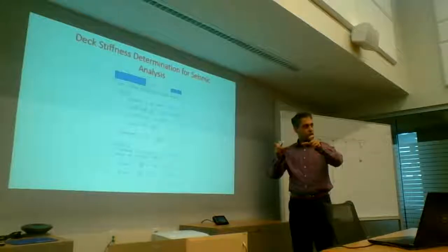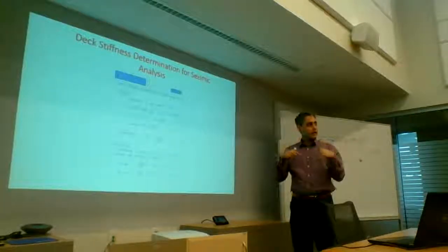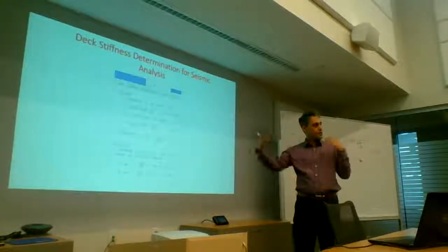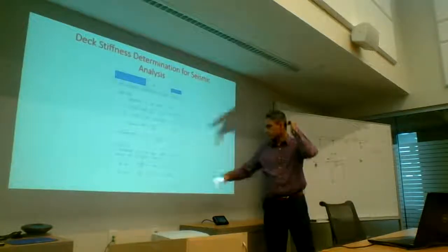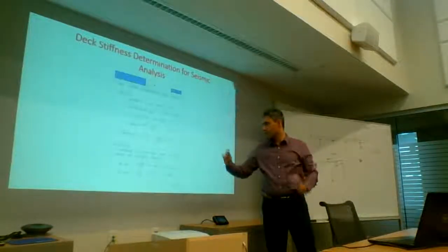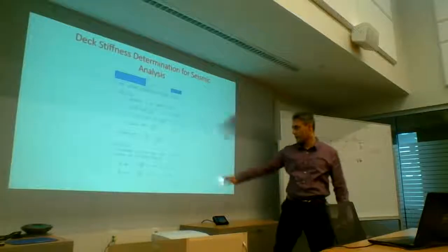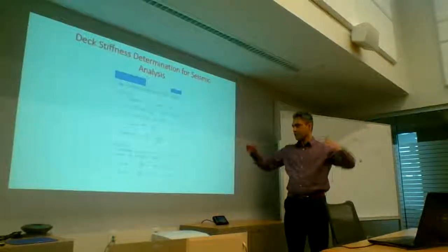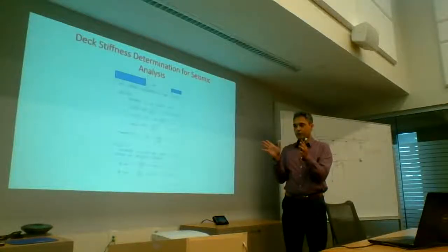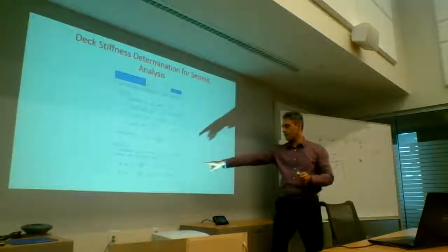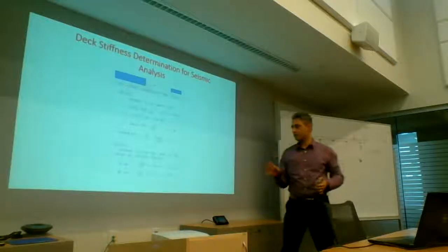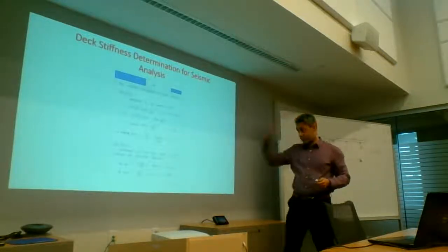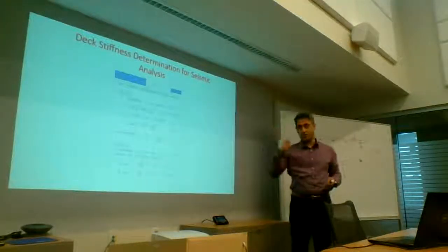When you're looking at your transverse section, now you're looking at reducing the thickness. So for vertical, you have this total width, which is 10.98 meters, and you divide it by 7.4, so your equivalent is only a slab which is 1484 wide, with the same depth of 225, but now it's steel.